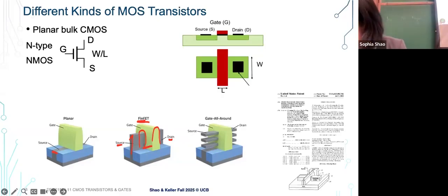And the more advanced technology, what people call gate-all-around or GAA, is not only just the fins. It's trying to have even more contact area by having this kind of very weird structure, you can almost feel like breaks there, but then you can wrap around all the different dimensions. So there's still more channel area being conducted, without continuing to shrink the channel length. That's some of what the more advanced fabrication folks are trying to do these days.